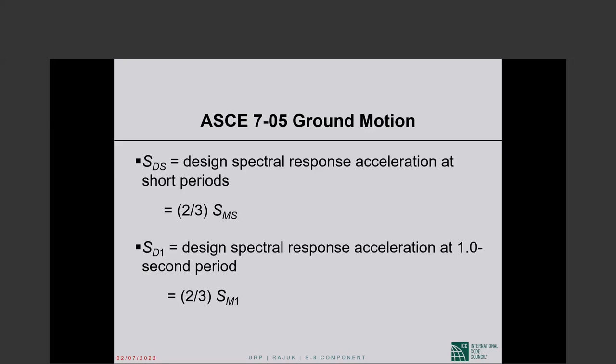The 1.5 is the lower bound margin of safety that we believe is available in all structures designed by the modern seismic code, which by common acknowledgement dates back to the 1977 UBC, Uniform Building Code, the edition that followed the 1973 Uniform Building Code, the edition that followed the 1971 San Fernando earthquake.